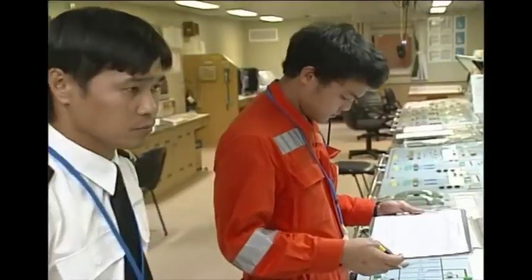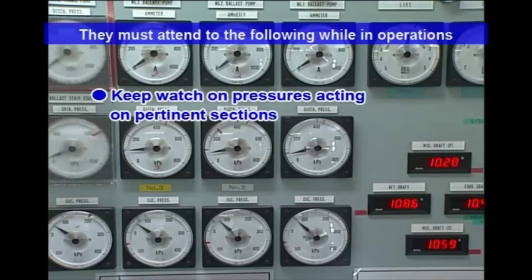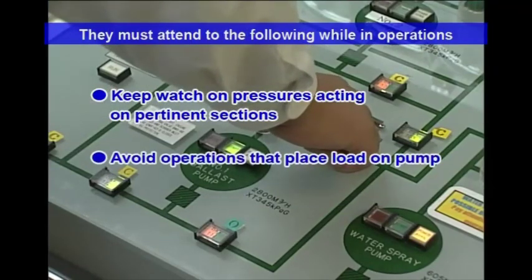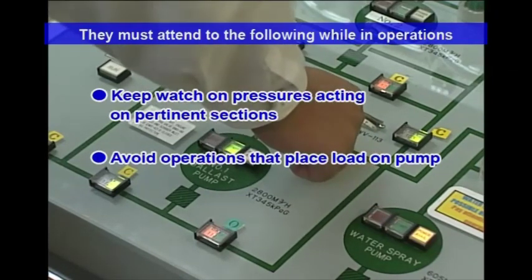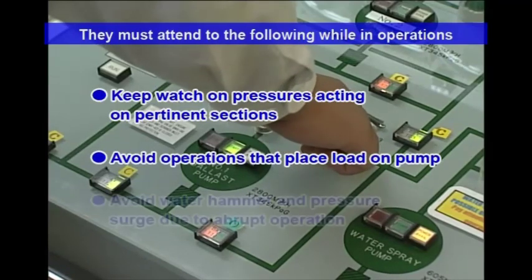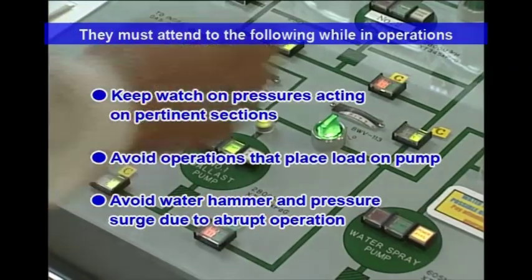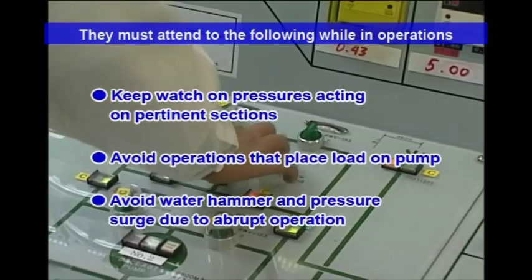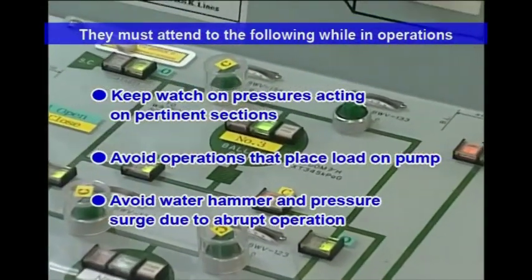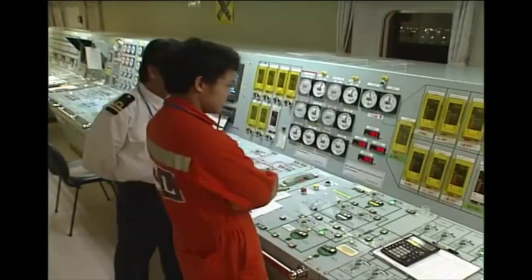Especially, they must attend to the following while in operation. Keep watch on pressures acting on pertinent sections. Understand the pump's principle and avoid load-placing operations, such as cavitation and air drawing. And understand valve characteristics and avoid water hammer and pressure surge due to abrupt valve operation. Keeping an eye on and securely conducting operations with these points in mind is the key to ensuring safe